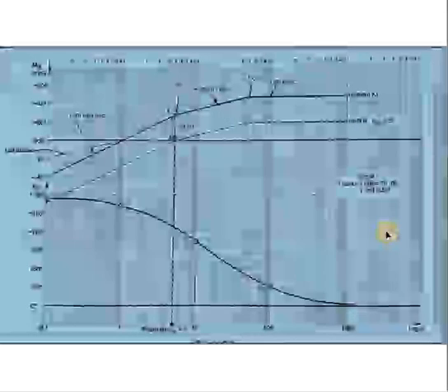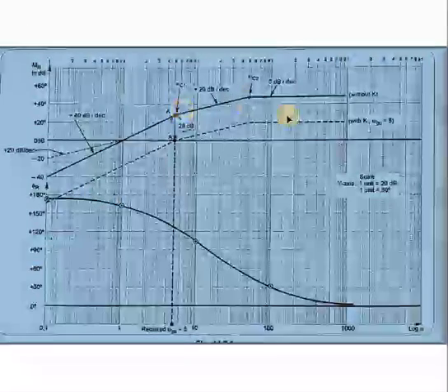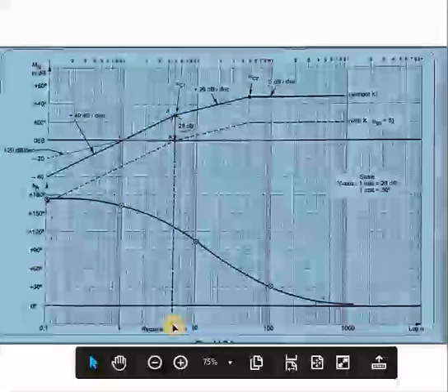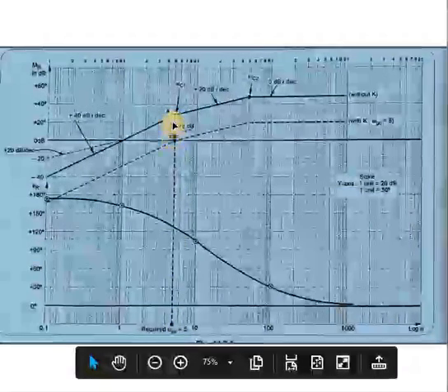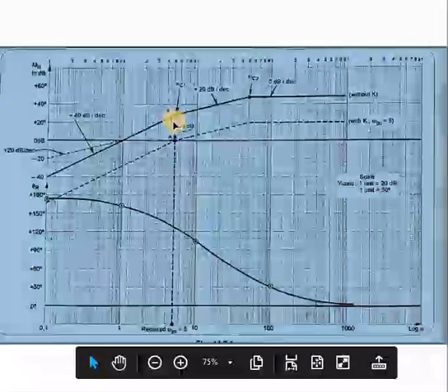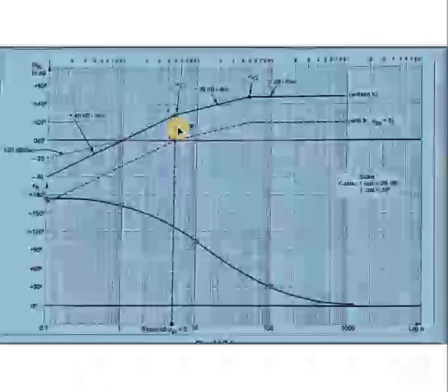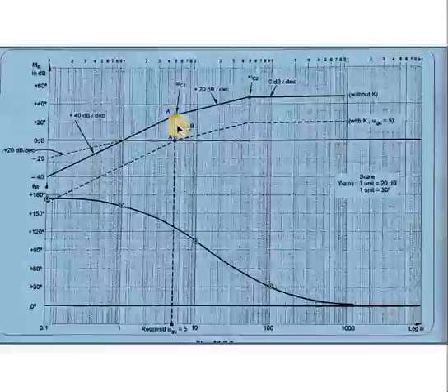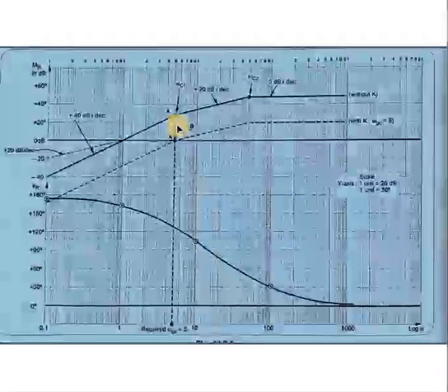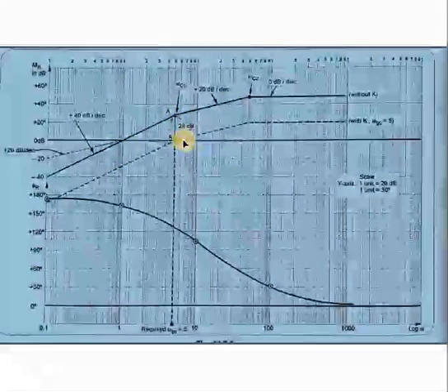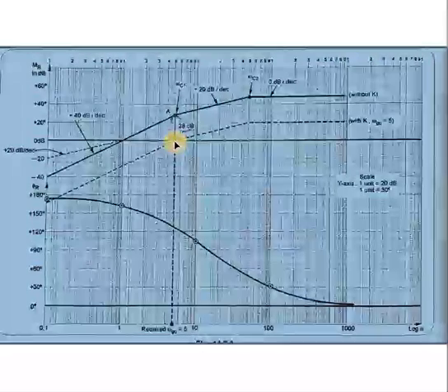Okay, so here the only thing is, after construction of this magnitude plot, first you have to mark omega GC at 5 radian per second. From there you need to draw a vertical line up to this magnitude plot, and whatever the distance is there, that distance you need to measure, and you equate that distance to 20 log K. From that you have to get the value of K, and you have to shift this entire plot to this point.